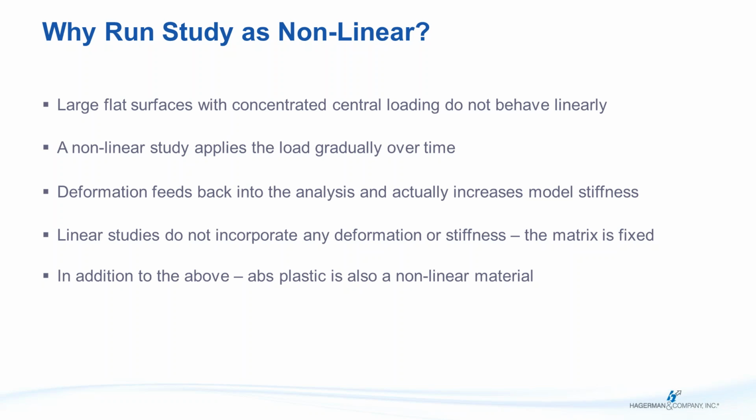Nonlinear study specifically applies the load a little bit at a time, whereas a linear study is just a thud. It applies the load and that's it. You don't get any kind of gradual introduction of the load. So with a nonlinear study, maybe we don't hit the 300 pounds, but maybe we hit 260. Is that good enough?